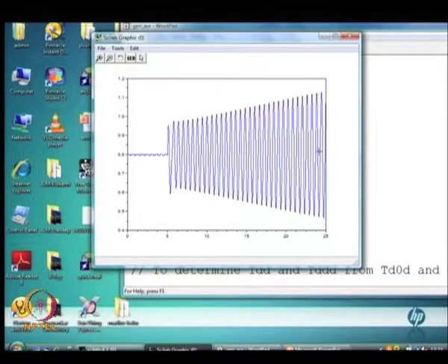Since it is a pulse change in Vref, Vref is brought back to its old value. So, we would expect that the system should settle down to the same equilibrium as before this pulse change. But this does not happen. The oscillation simply does not settle down, and we have essentially what you would call small signal instability in this system.